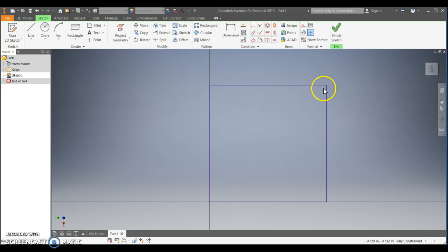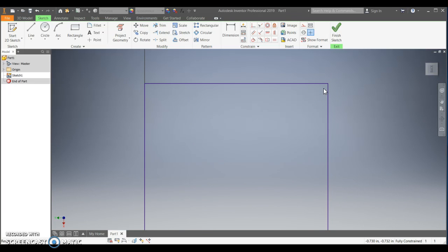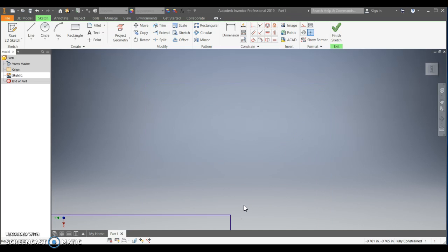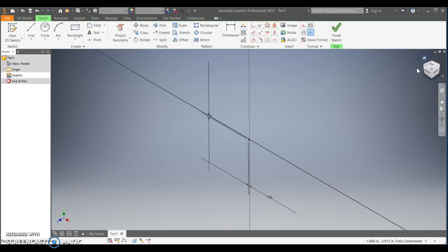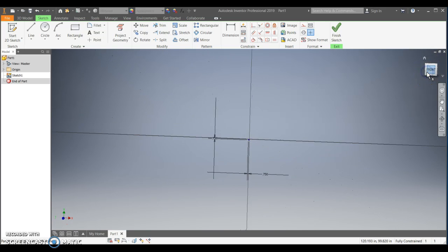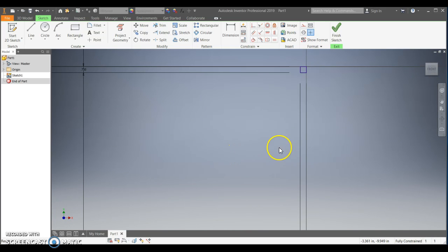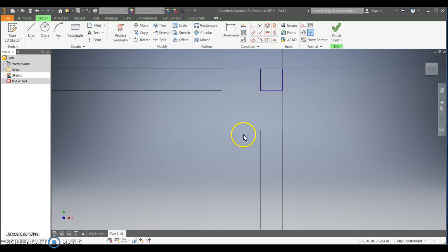If I want to go to another area, zoom in, so forth and so on. So it will zoom into anything. So if you're wondering why your object disappeared, it's because you are zooming in to some space of the workspace. And if you still can't find it, just press the home button. It will immediately bring you to your drawing.